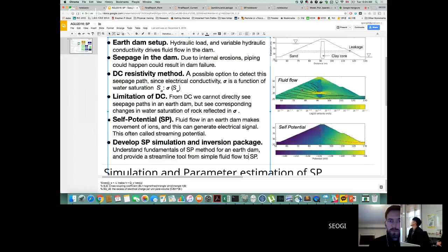Right. So here I think what I did is I solved this full domain and computed the pressure. Actually, I solved for hydraulic head, and then you can compute the pressure by subtracting the height. Then you find the zero contour. So I'm assuming above this, it's zero pressure, meaning there's nothing happening. But it's not quite right.